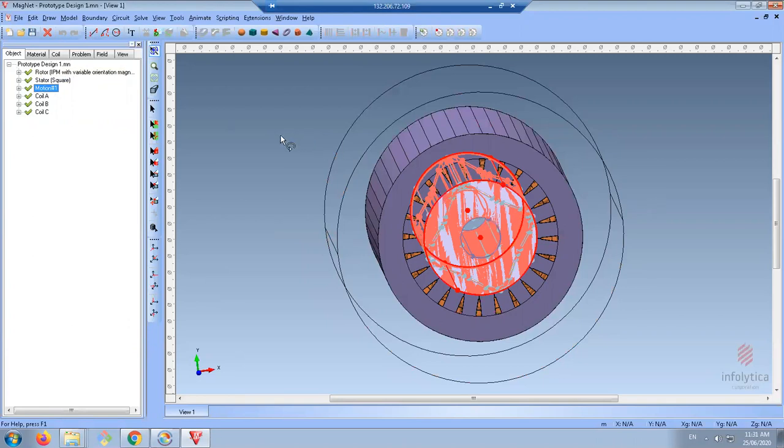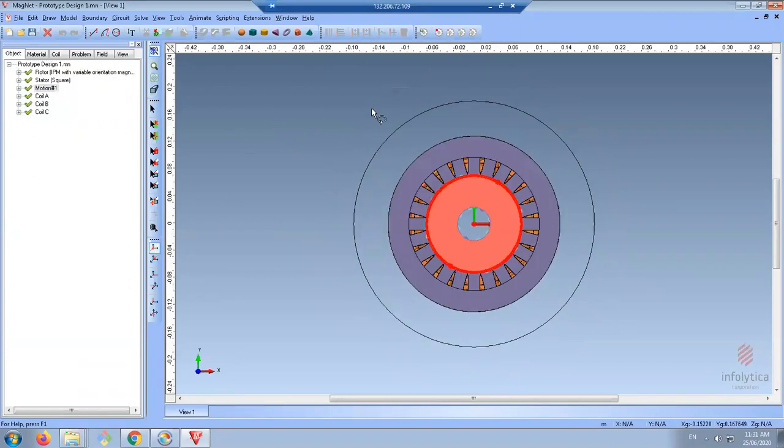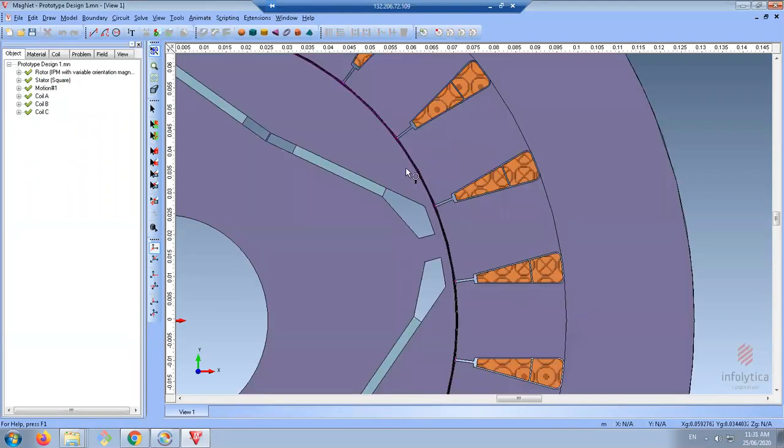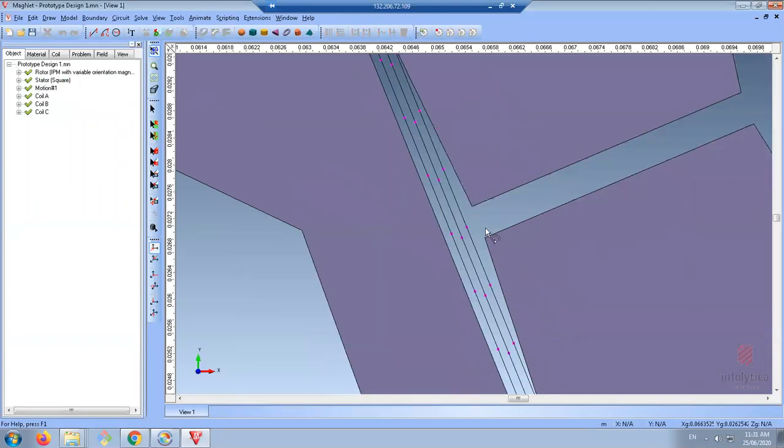which consists of the rotor components as well as a part of the air gap. This is very important. To guarantee that we have a stable torque computation, we always discretize the air gap. This is the air gap, right? This part is the rotor and this part is the stator core. We discretize it to at least two parts, the rotor side and the stator side, but it's better to increase